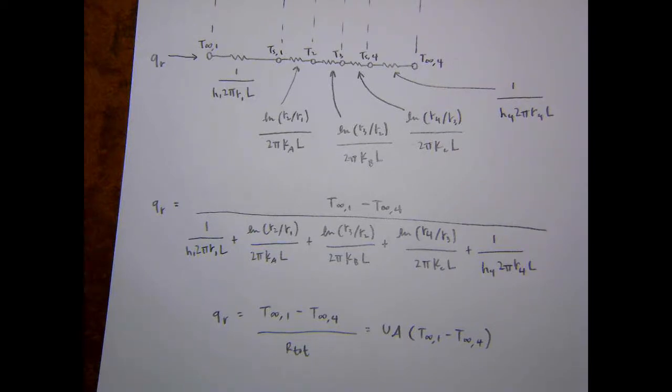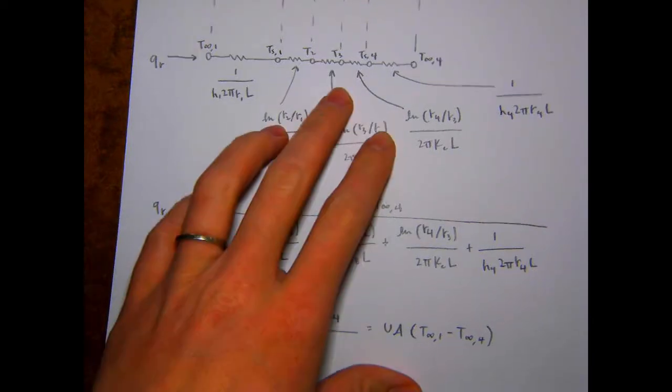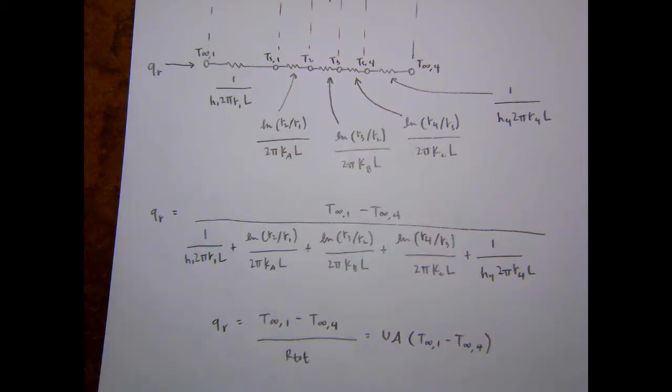So anyway, if you look at temperatures in parallel like that, you can do an analogous thing where you have your resistances and you treat it just like you would in a circuit. Anyway, we were talking about how you can have constant heat transfer rate through these different materials. If you've got convection, you've got a constant surface temperature, and then convection, whatever. You can use the heat diffusion equation to derive the temperature distribution within your solid, and either you have constant surface temperature or convection on the boundaries.